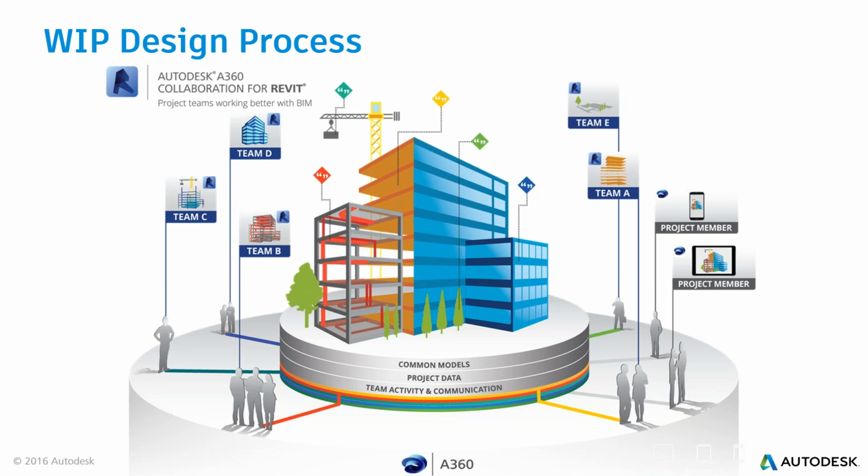So that's great for everyone who's looking to manage those documents, but how do you manage that work in progress design information? You may be aware of collaboration for Revit. For those who are aware of Revit Server, think of this as Revit Server within the cloud. This is the next generation of Revit, which allows you to communicate between different offices around the world, or even just across the other side of the desk, and it would allow you to have your Revit model within the cloud and manage those revision cycles with work sets available to certain users with certain permissions.